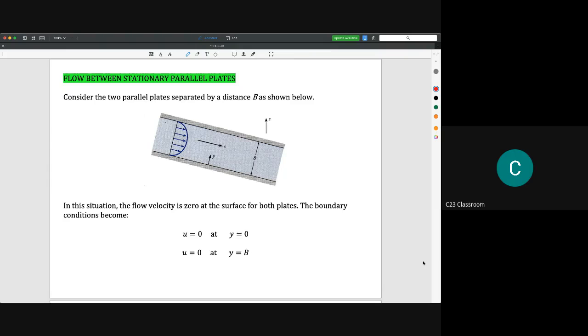Okay, we continue our lecture on the Couette flow, but now we go for the third condition, where the flow is now between stationary parallel plates. In this condition, we need to take care about the pressure. We cannot make a fast decision to neglect the existence of pressure, because the meaning of parallel plates here might be that you are now conducting a duct in a square shape.